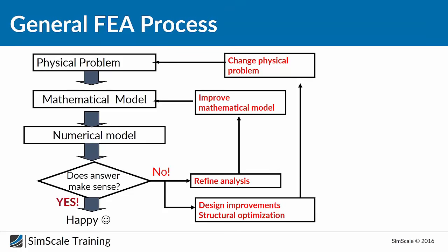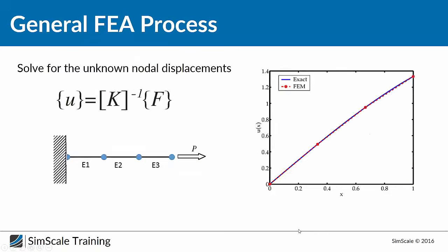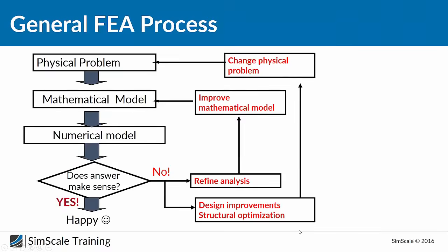And in the case the answer makes no sense, there are a lot of possible reasons. First of all, the reason can be that we need to make design improvements or change the problem. To give you a very simple example, just imagine you have designed something which should work under linear elastic material behavior, and your simulation crashes. Then one reason can be that your current load case is outside this linear elastic behavior.